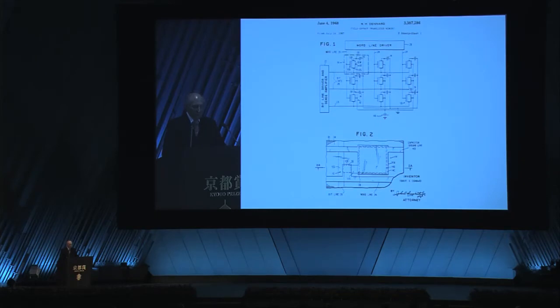I finally got a chance to work on my one transistor dynamic RAM scheme in 1970, when a new project was started at IBM Research with the ambitious goal of drastically reducing memory costs by combining the simplicity of one transistor memory cells with a substantial reduction in all the transistor and wiring dimensions of the integrated circuits. My longtime associate, Dale Critchlow, was the leader of this program. We wanted to take advantage of dramatic advances in lithography techniques which were being developed at our laboratory, such as electron beam pattern writing, which we felt could reduce the dimensions used in integrated circuits by a factor of 5.